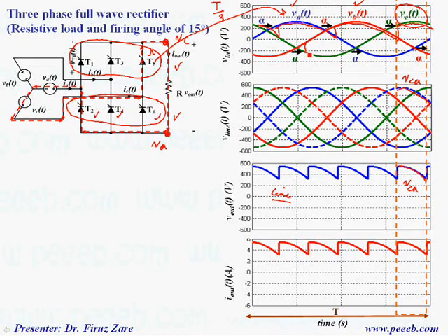That means we have this voltage generated by the bottom group of thyristors, and then this terminal equals this voltage, and this terminal equals this voltage. So what's the output voltage? Output voltage is this terminal minus this terminal, which is basically line voltage. So at any time, output voltage is this voltage minus this voltage, which is basically line voltage.